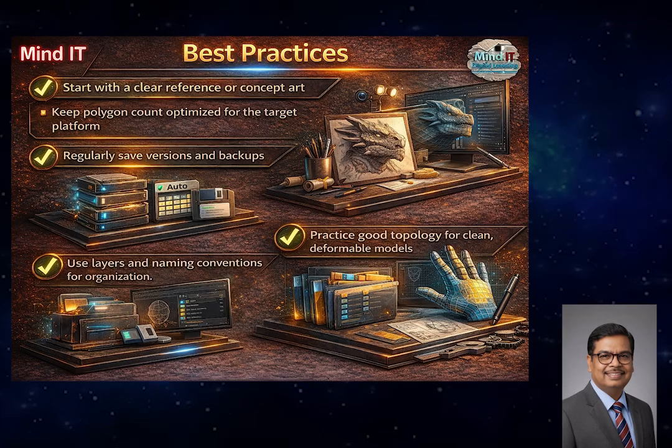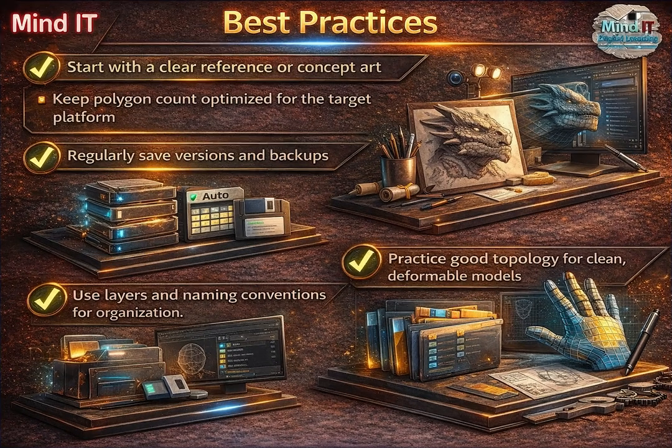Best practices. Start with a clear reference or concept art. Keep polygon count optimized for the target platform. Regularly save versions and backups. Use layers and naming conventions for organization. Practice good topology for clean, deformable models.